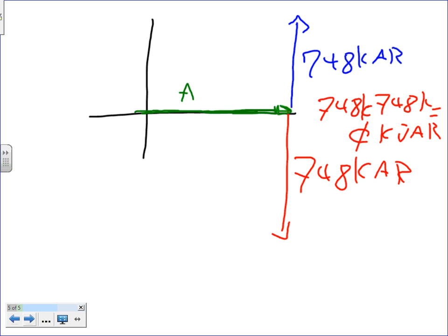So the apparent power equals the true power. What was the true power, Brad? 500 kW. Now, can you guys see it's as if this triangle kept going down, down, down until the apparent power equals 500 kVA? The apparent power and the true power are equal. Can you guys see that? The triangle kept going down until they match. That's the ideal situation.